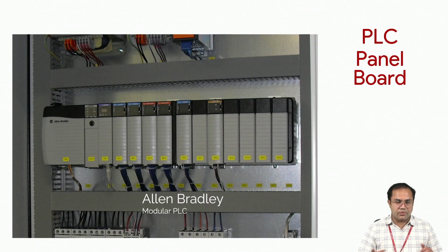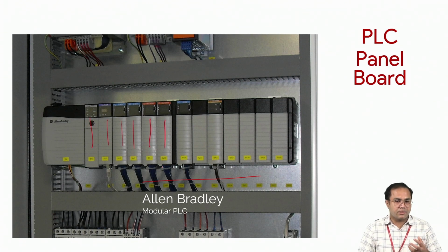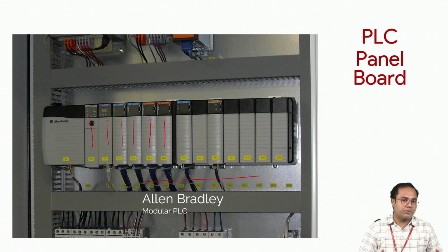Now, as we are in the digital era, those entire relay boards are replaced with this modular PLC. Why am I saying this is modular? Because here these are the modules, the input output modules. I can customize the PLC according to my application, according to my requirements. How many inputs and how many outputs are required, based on that, I can customize the PLC.